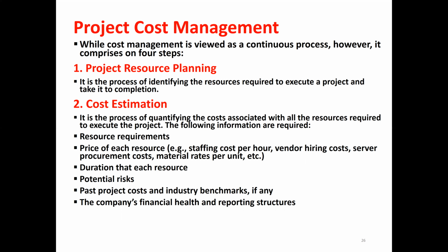Then the duration that each resource will be utilized. What are the potential risks? Past project cost and industry benchmarks, if any. So we should consider what the past project costs and industry benchmarks are while putting our profit into the estimation. Also the company's financial health and reporting structure. So in the cost estimate, we have to consider the company's financial health and reporting system, how much our overheads or indirect cost and profit margin should be, while preparing the estimate.